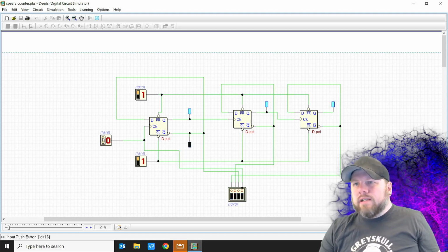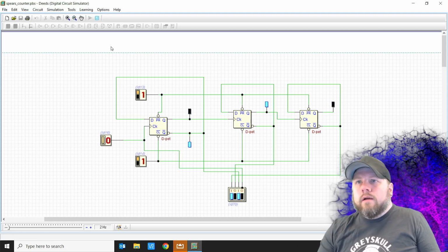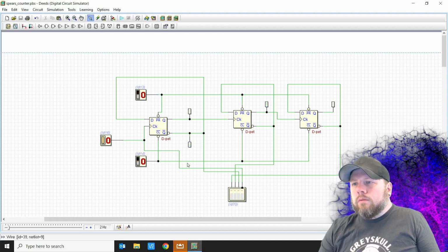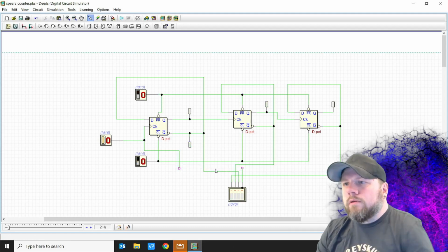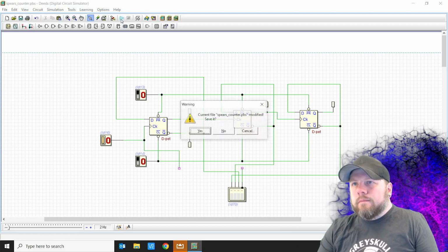We had something squirrely because I guess I pushed it twice. But notice what's going on down there. I'm counting in binary. 2, 3, 4, 5, 6, 7, 8. If we ignore this right here, let's take that wire out real quick, because we're getting a little stutter because these are all edge triggered and my finger is not, all right?